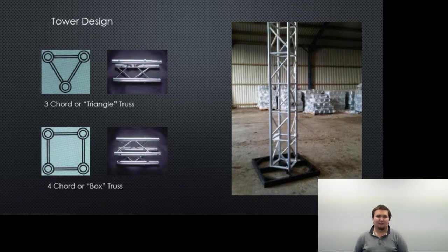The design incorporates a sleeve that slips over the top of the legs on the bottom half. The legs on the top half then also slide into the sleeves and are pinned in place to hold them in position. In regards to tower sizes, we have decided upon a tower height of 2 metres and length and width of both 0.25 metres. Sizing the towers to these dimensions means that they are large enough for our purposes, while still being a manageable size if we are required to relocate the tower indoors in the case of poor weather conditions.